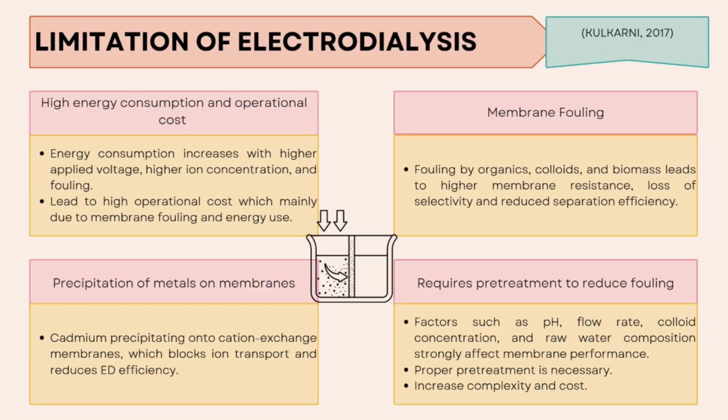The energy requirement increases when the feed voltage or ion concentration is high, and it becomes even worse when fouling occurs. Because of this, the overall operation cost rises significantly, mainly due to both membrane fouling and the high energy demand. Second, membrane fouling is a major challenge.